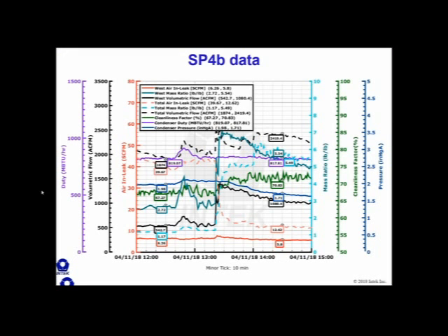And so here's the data after we got that fixed. This is very busy, but let's just focus on one parameter, one color of data, and that is the red data. I think that should say east, but anyway, there's two air in-leakage values: the solid red and the dashed red. You can see here that once that drain was plugged, the air in-leakage value plummets back down to a low value of 12 SCFM. The other side has 5 SCFM.